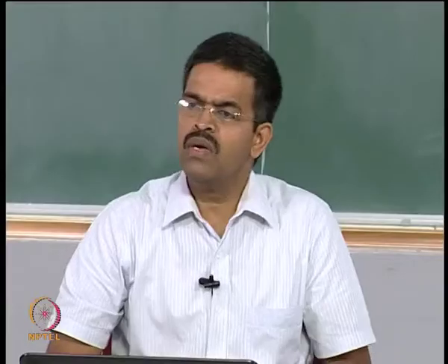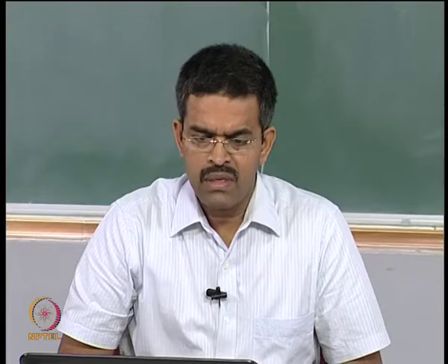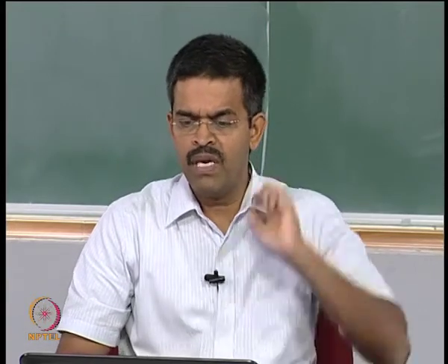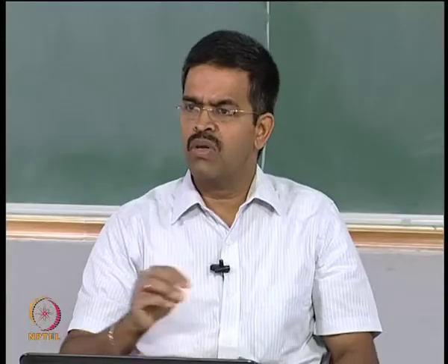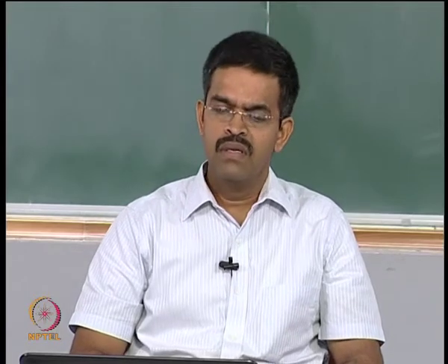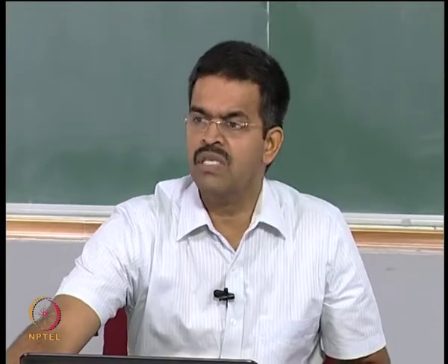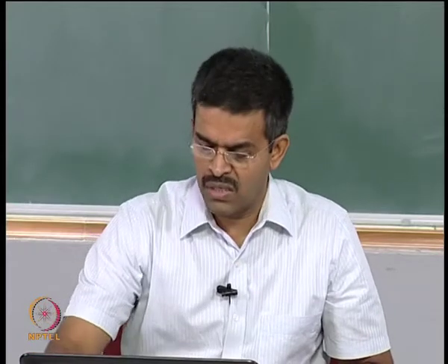So, from the table one can easily identify that the force reduction is significant in short period waves compared to long period waves. The force variation is significant, and we have also seen that this variation is non-linear, as it is not proportional either to the increase in wave height or to the change in wave period. It is also understood that different layers of A, B, C configurations have been put on the inner cylinder. The size of perforation is also different for A, B, C, as you can see in this table.